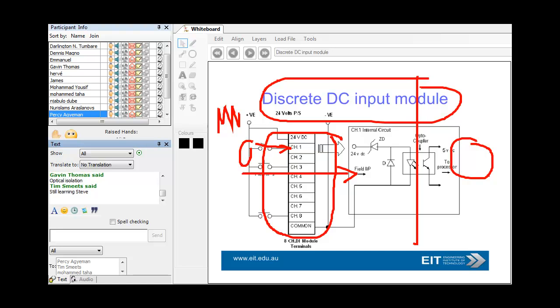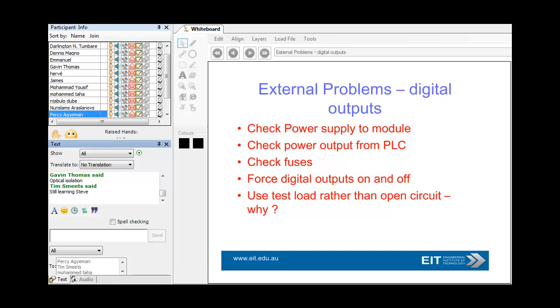There was nothing near it. It was a tricky problem and quite difficult to fix because we had a lot of these little proximity detectors, and they had sufficient leakage current to bias the inputs on. So the input should be off, and I saw it as off from the proximity detector, but there was sufficient leakage current within the legs of the PLC to say, hey, I'm still on. And it's actually off. Those are tricky little problems, leakage currents.